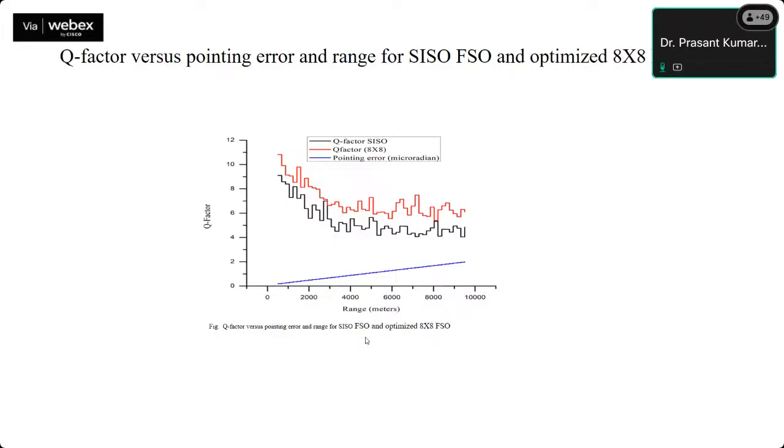This is the one where we applied the chaos, and we have used here a triangular chaos based system. The chaos we designed is a triangular chaos, which is used to directly modulate the semiconductor laser diode, and the output of that is added to the MDRZ signals. Once we transmit that chaos added signal, at the receiver side we need to use a coherent scheme to demodulate, whereby we use the same chaos generated to subtract the signal we added at the transmitter side.